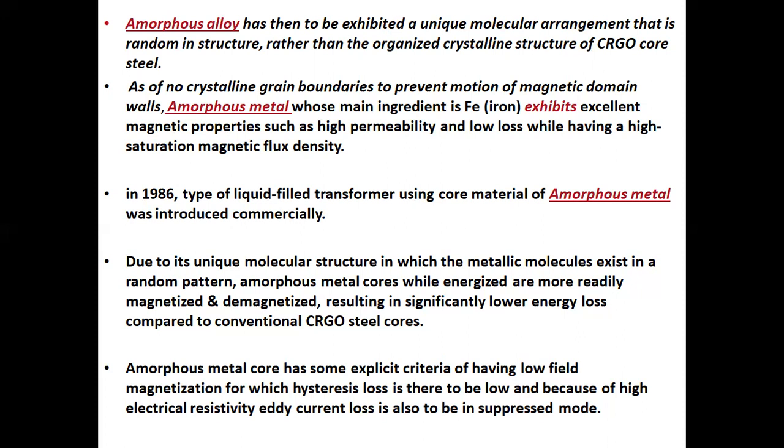Amorphous metal core has some explicit criteria of low field magnetization, for which hysteresis loss is low, and because of high electrical resistivity, eddy current loss is also suppressed.